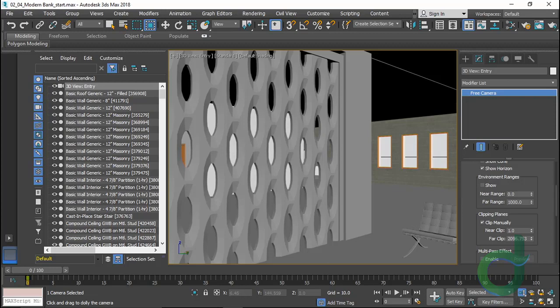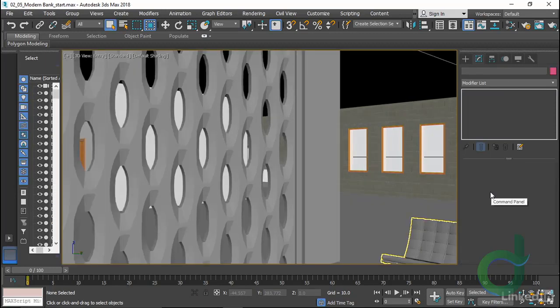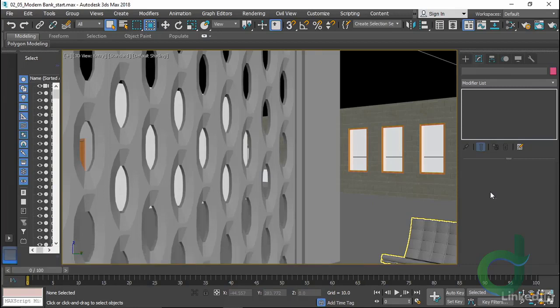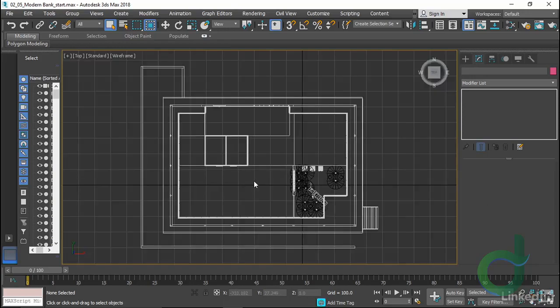Creating good terrain is a thorny business between Revit and 3ds Max. Often Revit terrain can be a little blocky or not come in correctly at all. We need to make sure we have good terrain, and in this particular building I need some gently sloping areas of terrain that I can plant. I'll take a look at some reference imagery on the original to see what the terrain is around this building. Quite often, I'll have maybe proxy terrain or at least loose guidelines in Revit, and then really, for a rendering, put it together in 3ds Max.